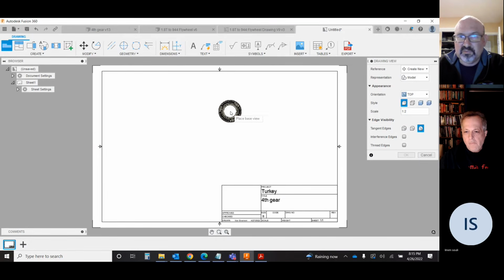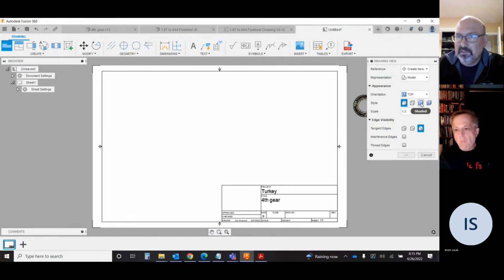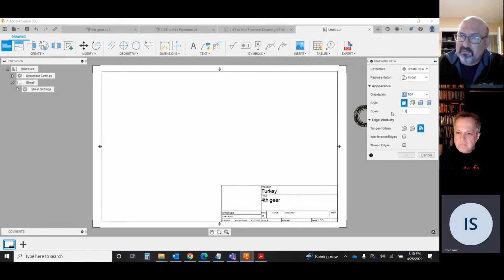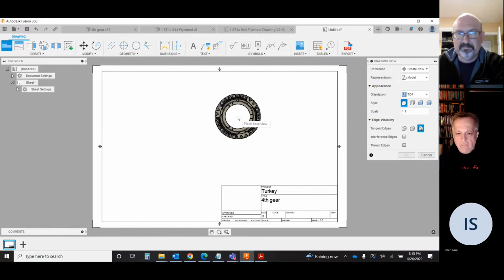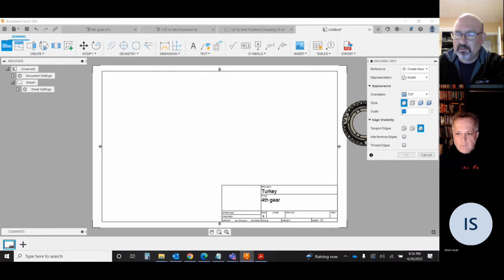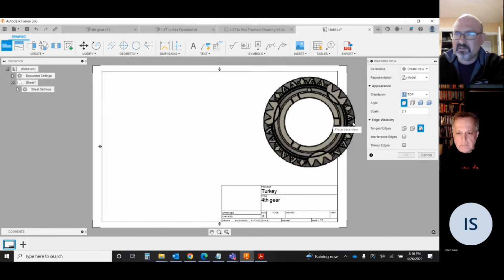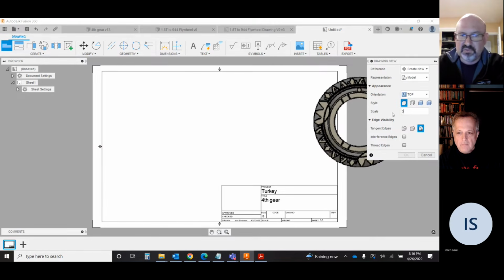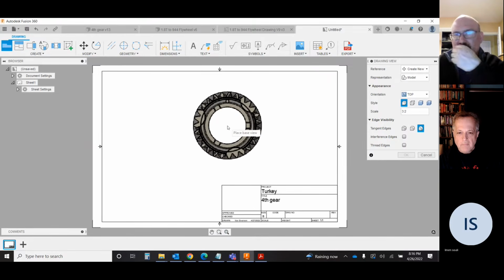So that's a front. This would be the top view, and then there's also a scaling factor. There's also options for if you want to display it as a solid or with hidden lines or dotted hidden lines or no extra lines. For this, let's make it 1:1 maybe. What size does that look like? Maybe even a little bit bigger. To 2, is that too big? Oh, I'm sorry, 2:1. That's too big. Maybe 3:2. Yeah, that might be good to start off.